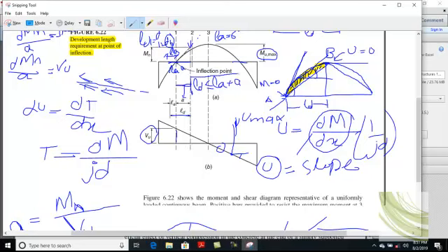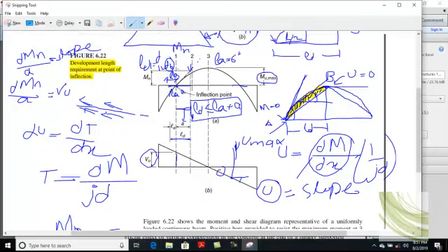This means, as I mentioned at the beginning, that at point 2, if the bar is extended from point 3 to this point of inflection by a distance of Ld, the moment right over point 2 has only a remaining development length equal to half of the total development length.